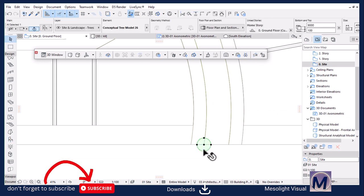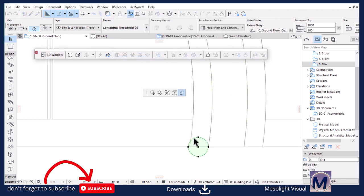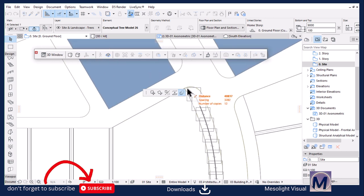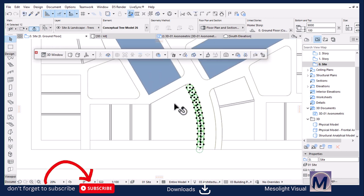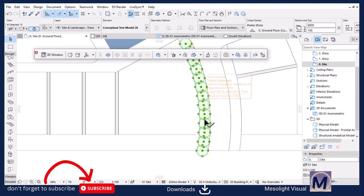I can just place it here, and then I can select it and multiply it. I'm going to use a path to do that, a path with an increment and spread under the drag command, and then hit OK. I'll select this line and bring it to the center of the object, and then I can run multiple copies like this. How cool is that? Boom. And then you can group. Make sure you take advantage of the selection and group them.